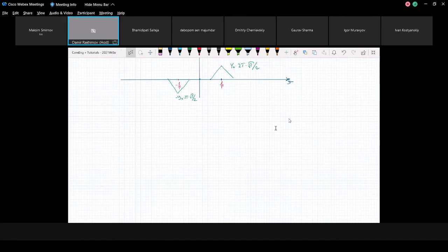Okay, so we come to the next part where we take our signal at intermediate frequency and mix it up again to the bandpass range. How do we do this? We take our intermediate signal at intermediate frequency and multiply by cosine of the frequency. And we need to draw this signal at the bandpass frequency. Let's try to do this.